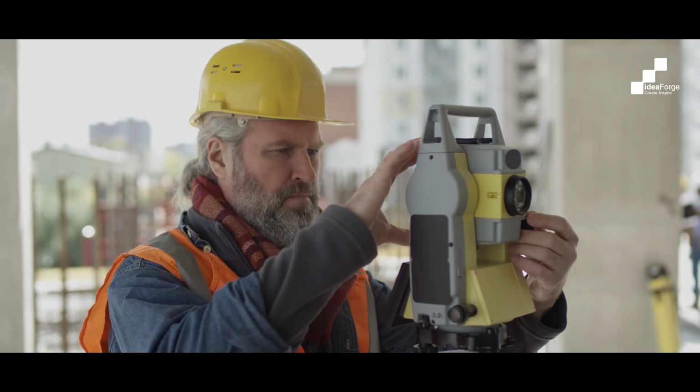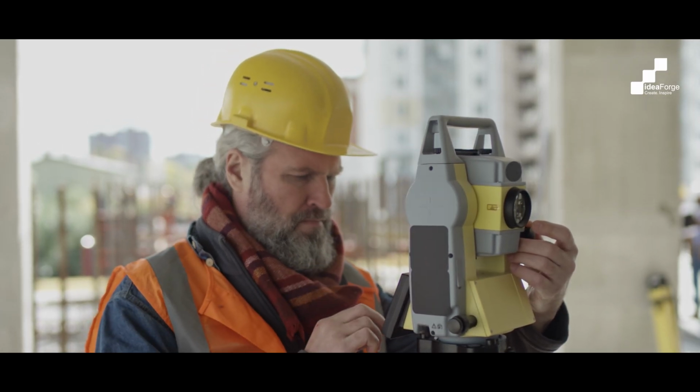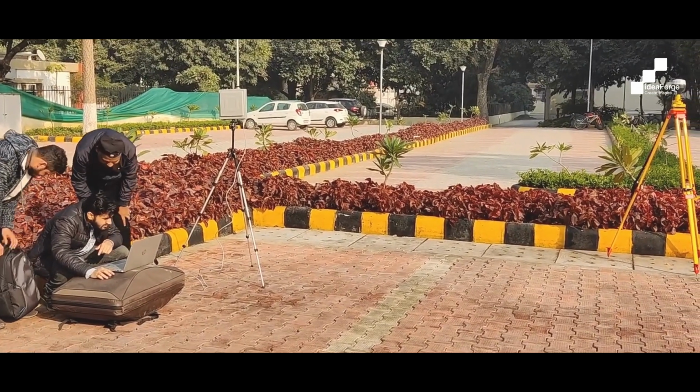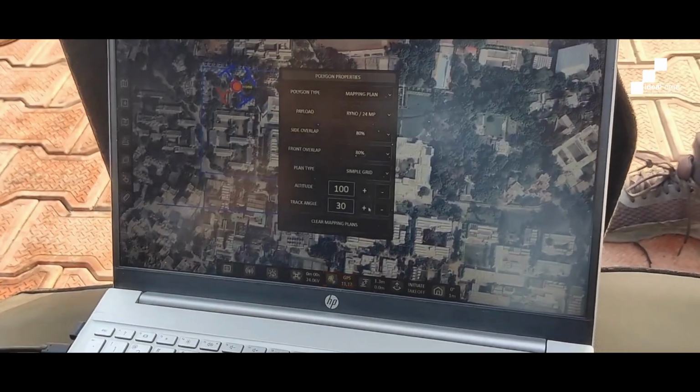So before we used UAV in our research group, we used total stations to map the landslide boundary. The total stations that we used took a lot of time, and we would spend almost the whole day in just mapping a few landslides. However, with the UAV, it takes a lot lesser time to go into the field and map these landslides. So in a day's work, we can map big and large landslides which are high in number in comparison to other instruments such as total station.